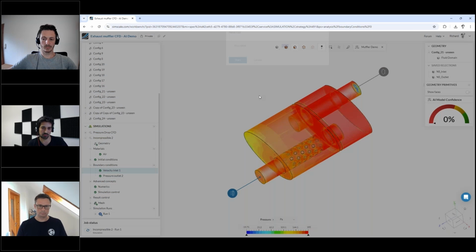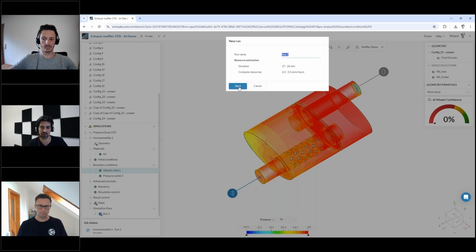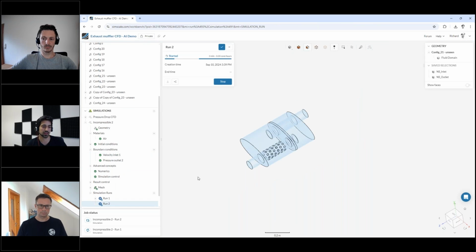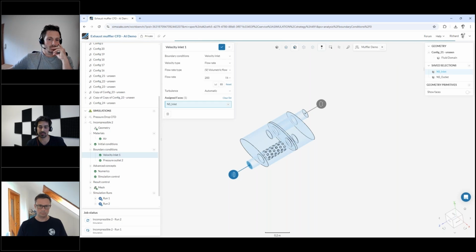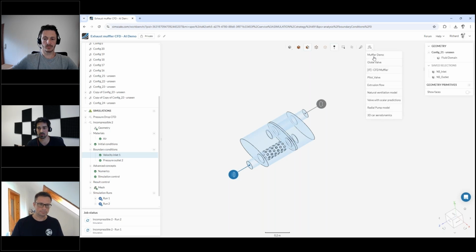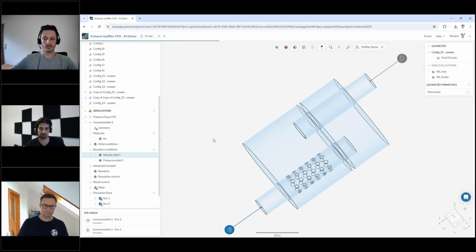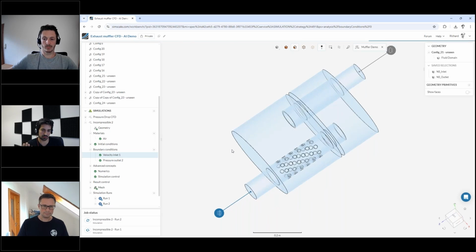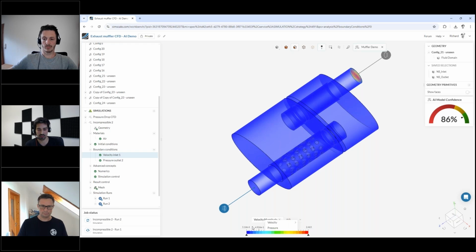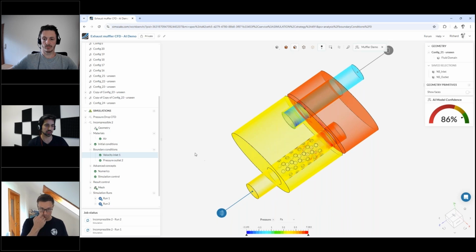You again get a prediction of the runtime, again about 20 minutes, and you can run now the normal CFD simulation, right? So this is the benefit of having an integrated platform where you have CFD and AI side by side, right? We can not only change the inlet conditions, right, and get a new prediction. What we could also do, let's now predict maybe on 10 liter. What we can also do, obviously, what is probably the most interesting part is changing the geometries, right, and see how different geometries perform, different designs perform under similar conditions.